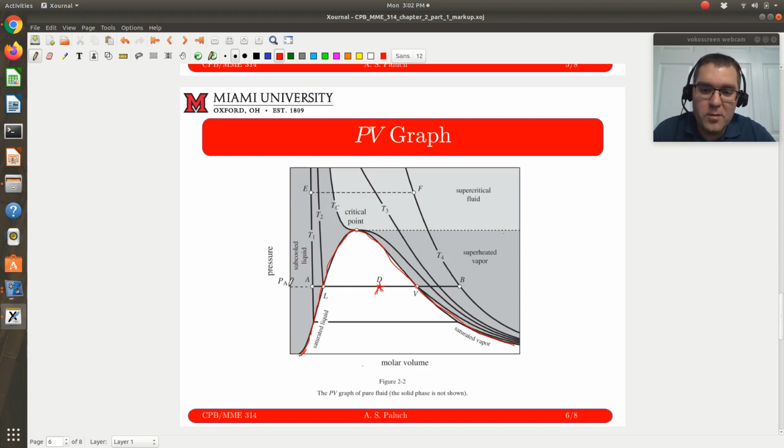isobar. What I mean by that is, here's pressure, here's volume. If the specific volume of my system puts me here, underneath the dome, I will get phase splitting. What I'm doing here is drawing a line across my phase diagram of constant pressure, because I know that my vapor and liquid at equilibrium will be at the same pressure.